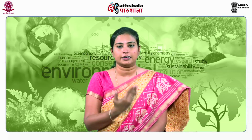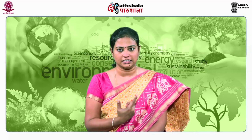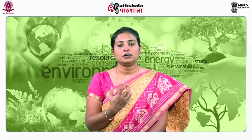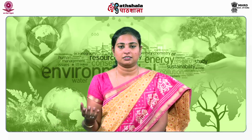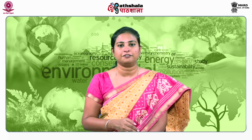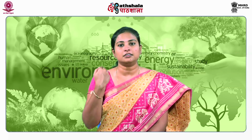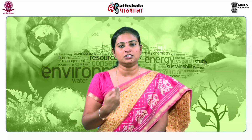That means it can be recirculated back. By doing so, it will increase the moisture present in the landfill. The moisture will accelerate the rate of decomposition and the rate of gas production. Also, it will favor the growth of microorganisms, and the partially degraded or undegraded materials present in the leachate will undergo further degradation when recirculated back into the landfill. So, that is the advantage of recirculating them. So, you can re-inject the liquid leachate back into the landfill for the above mentioned characteristics.